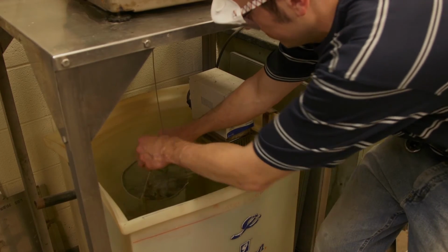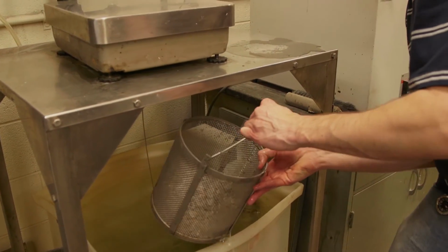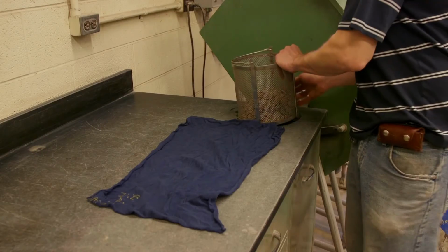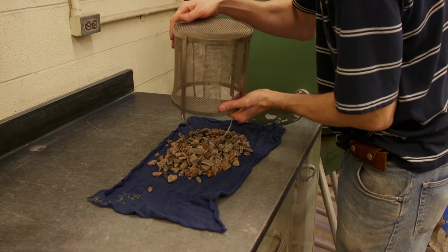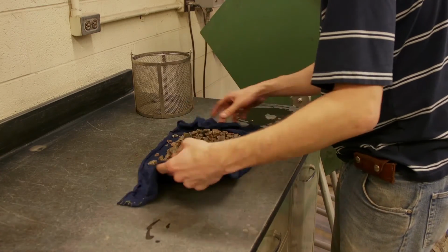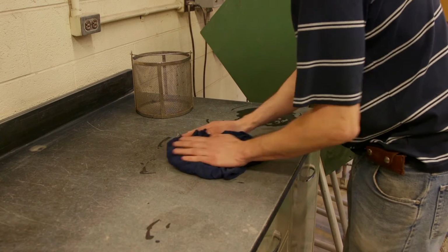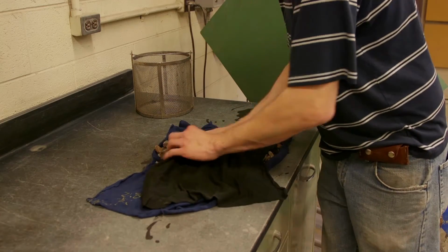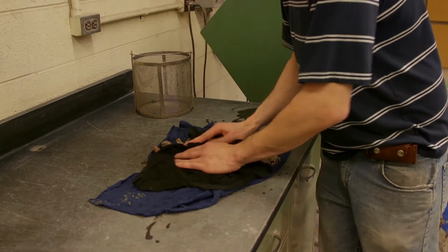Disconnect the basket from the scale. Pour the aggregate onto a dry towel, ensuring all particles are transferred from the basket to the towel. Roll the aggregate particles around on the towel until their surface is no longer shiny, but the particles are still wet. This represents the condition where the aggregate pores are filled with water, but the surface of the particles is dry. This is termed the saturated surface dry condition.